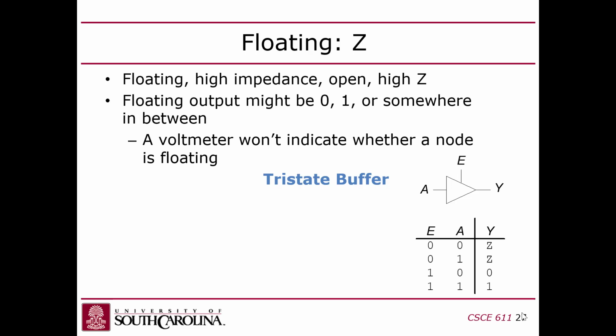You want more than one bus master, and you're only going to connect one bus master at a time, you can do it through one of these tri-state buffers where you can turn off the connection between the input and the output, right? And the way that's written in Verilog is through this Z value.